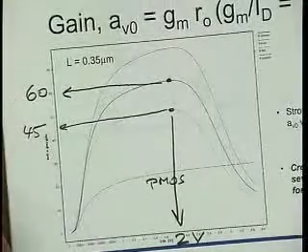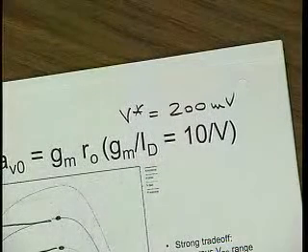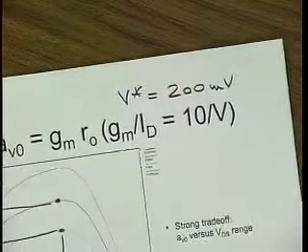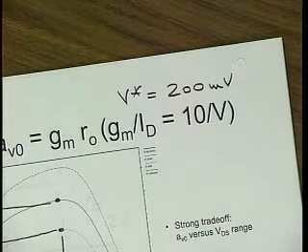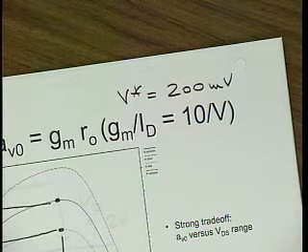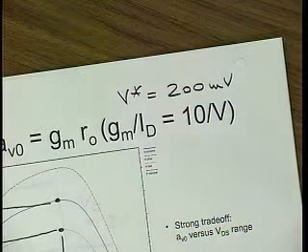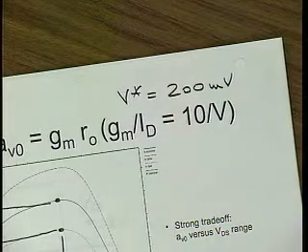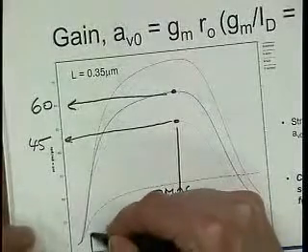Right? So the trouble is the VDS we are willing to give this thing. V star translates into V star equal to 200 millivolts, right? V star sort of again gives us this idea of VDSAT. So we ought to get into a high gain or high rout region when VDS is at least 200 millivolts. Let's be generous. We need to do a little bit extra, but maybe 300 millivolts. Well, if we go to 300 millivolts, we are here.